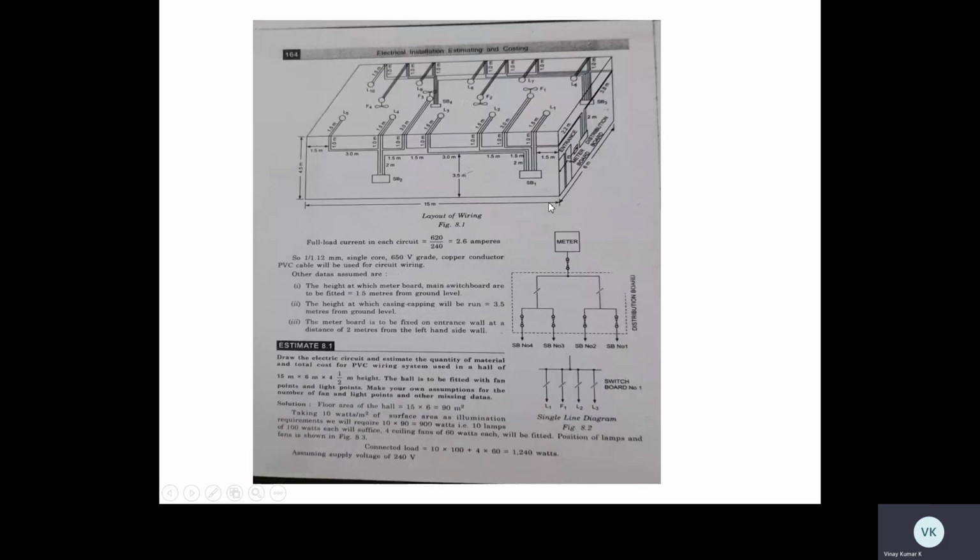So almost equal to 100 meters. We need 100 meters of PVC conduit. Okay, now come to the distribution board to switchboard SB1. How much cable do we require now? Till now we have calculated the conduit length. From now on we have to calculate how much length of cable we require, that is from the main distribution board to switchboard 1.